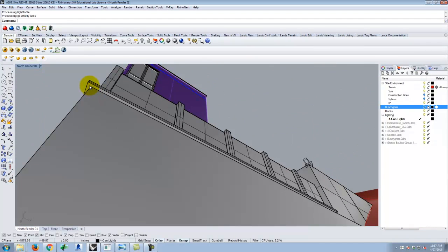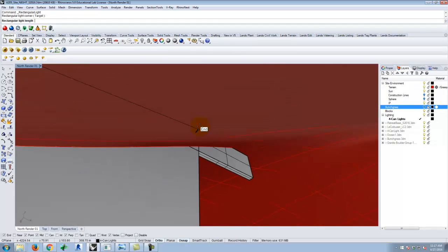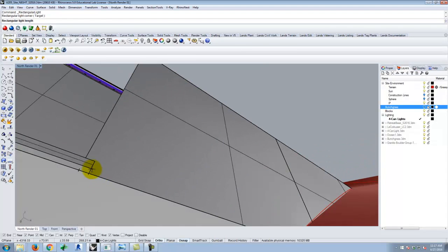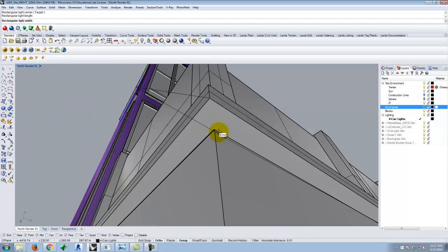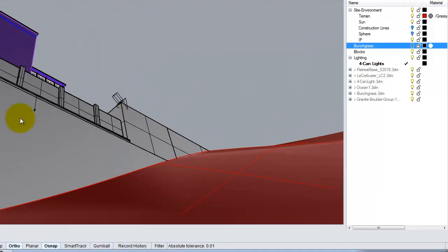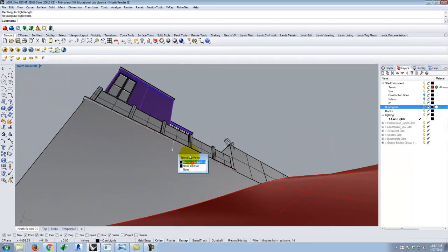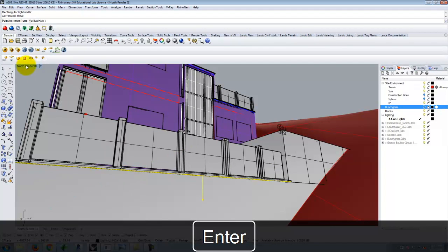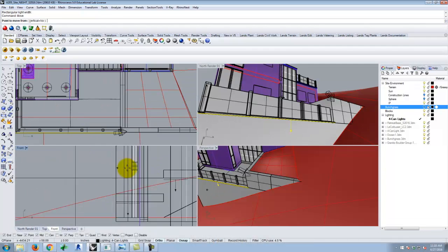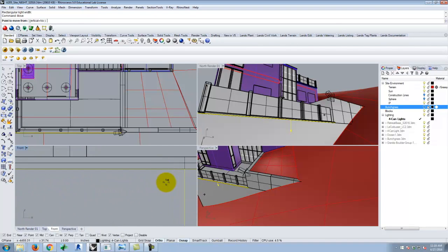I'm going to add some lights that tuck right underneath this little rail. So I'll use a rectangular light right here. And again, rectangular lights are always based on the overall size in terms of the wattage. So it's going to be a bit of a guess as to what's appropriate. So let me snap to that. And remember that that rectangular light needs to be down ever so slightly, so it's not coplanar here. So let me look in the side view, and we'll drop it down just a little bit.